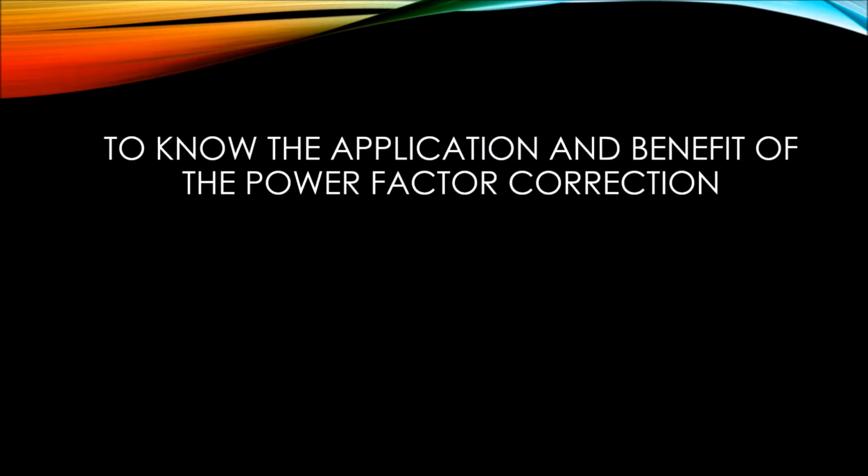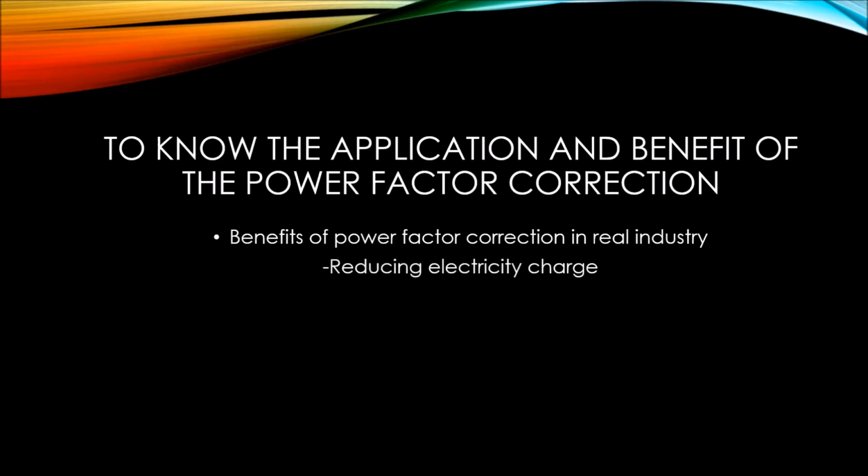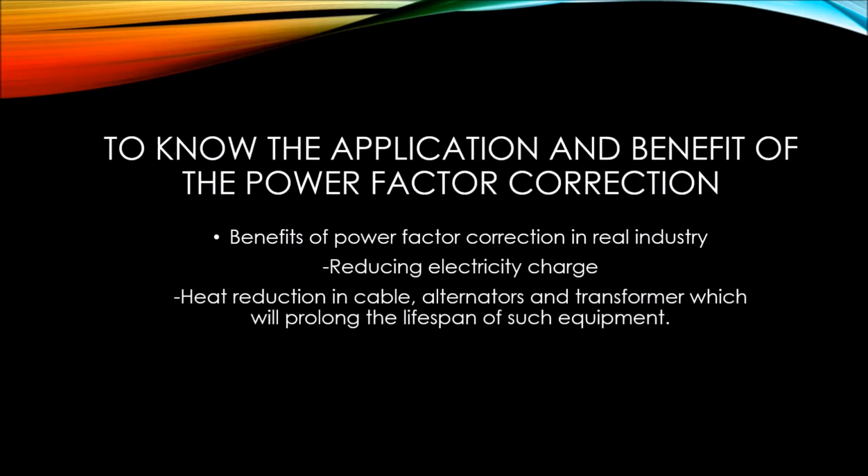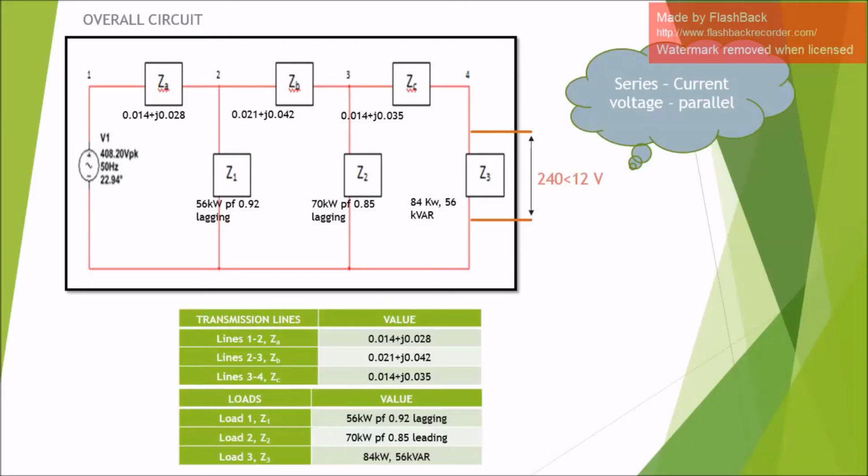And the last objective is to know the application and benefit of the power factor correction in real life. The benefits of power factor correction in real industry are reducing the electricity charge and also reducing the heat in cables, alternators and transformers, which will prolong the lifespan of such equipment. That's all for the objective.